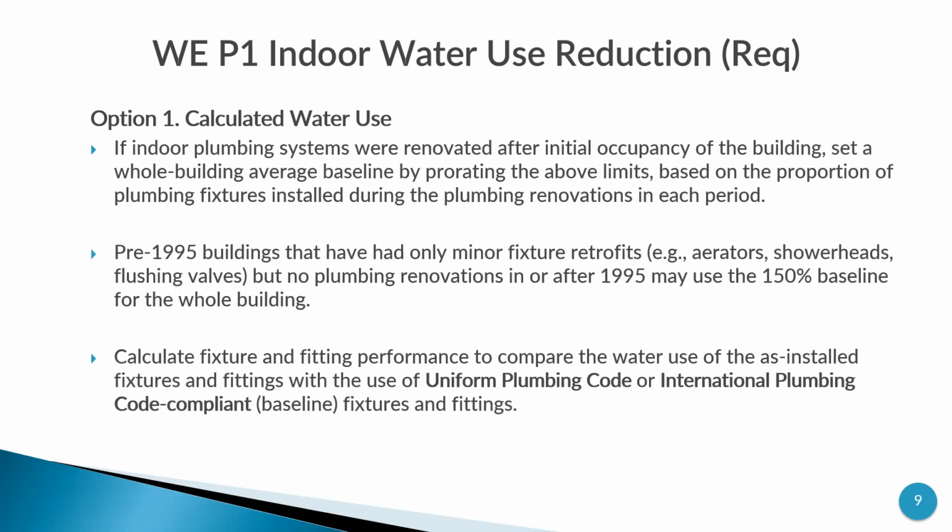Again, one question related to the previous one: I would like to apply this LEED O&M for my own company, office and building. So how do I measure how much each fixture and fitting is consuming? You need to test each and everything once, because it is an existing building, it could be of different brands, different models, not uniform. So you need to take those measuring toolkits, and then you need to measure.